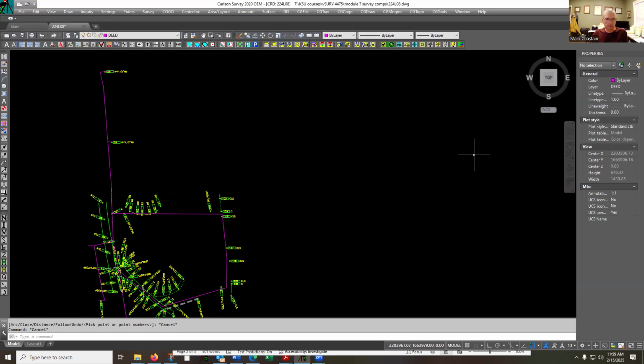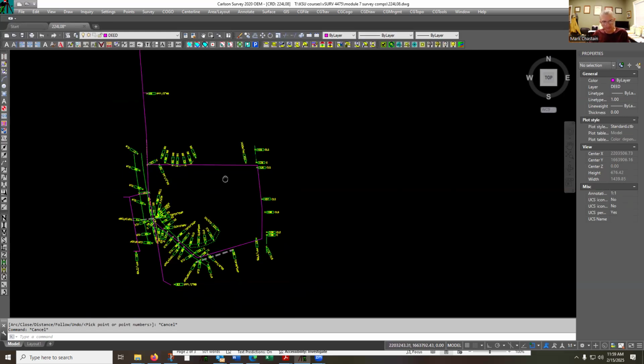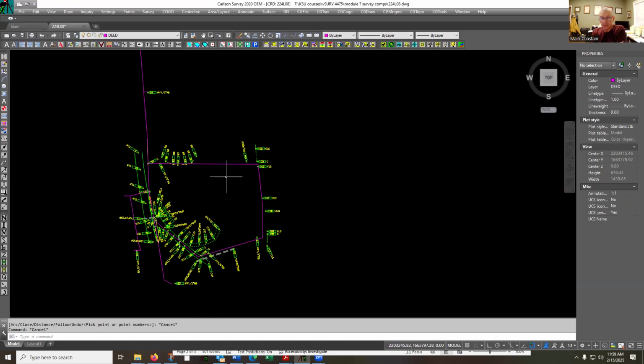All of our data here was rotated to grid north. Now, it's often a good idea to put out your work and to rotate in the same meridian that you're retracing. But what we find more and more is the benefits of using grid north means that future work snap in place a whole lot better. It also allows for using and importing georeferenced outsourced data, such as publicly sourced LiDAR data, georeferenced aerial imagery.